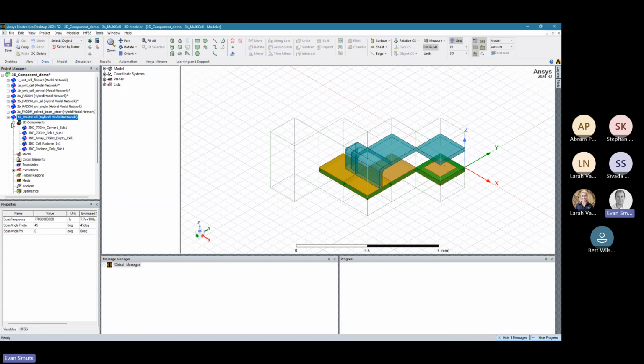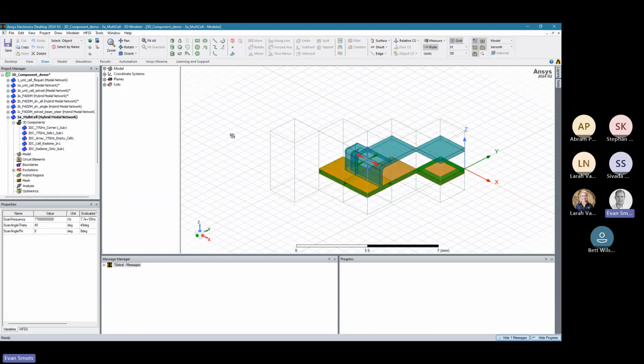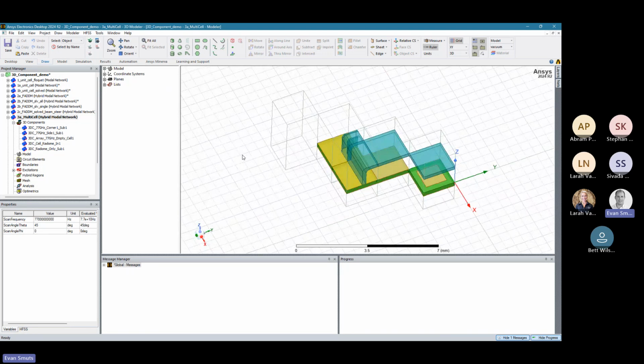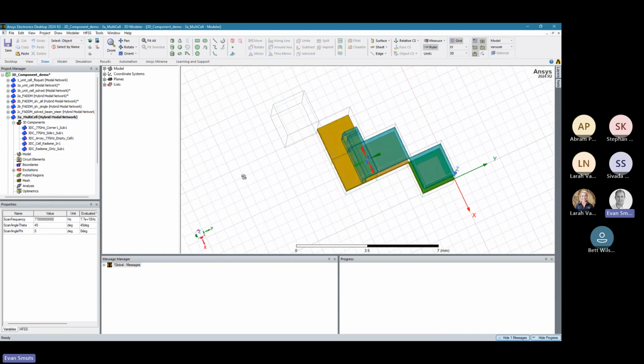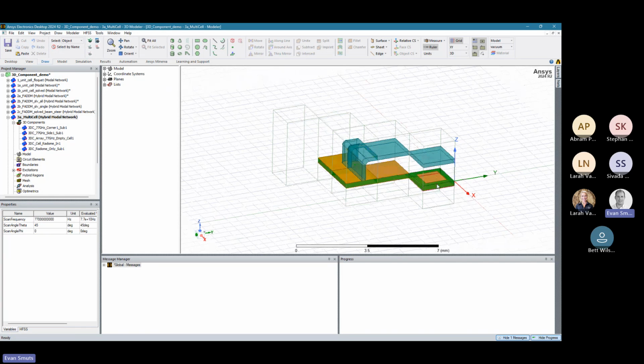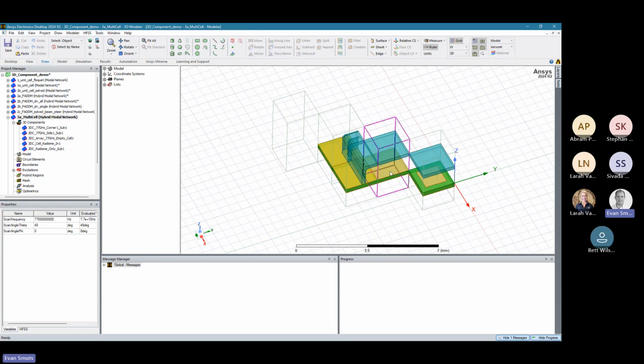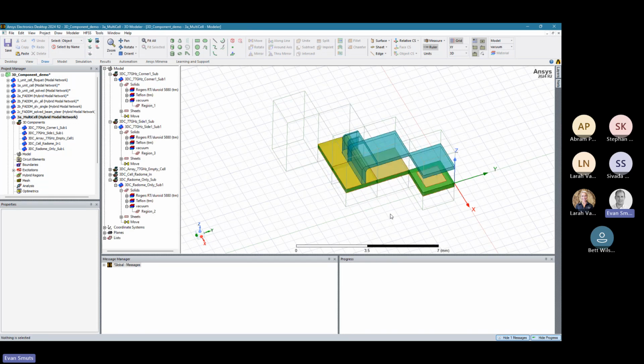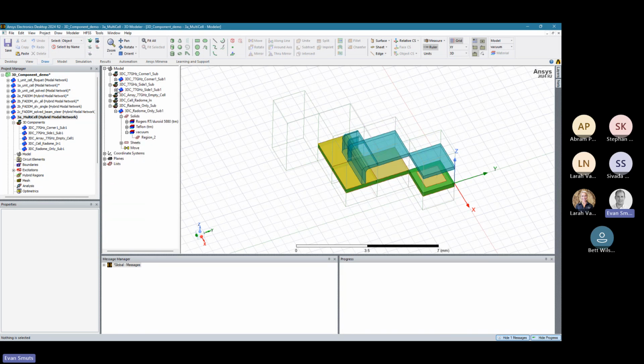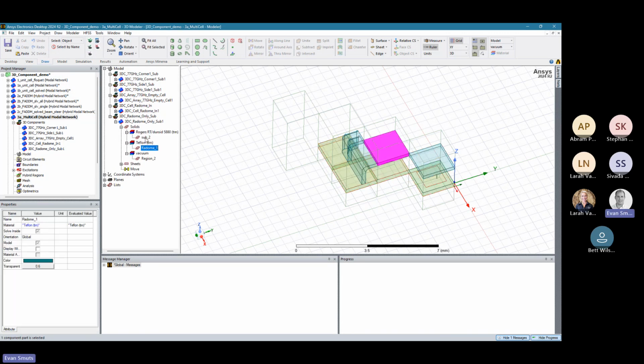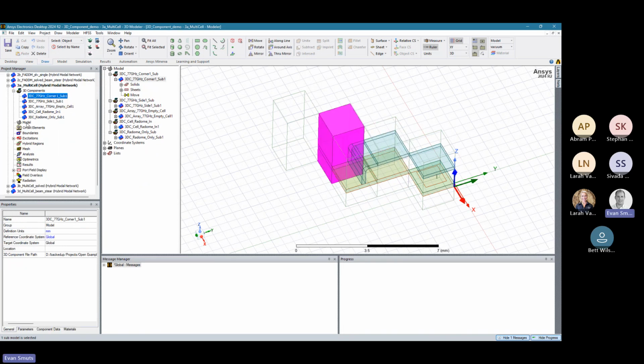And just lastly, to show you here for the multi-cell approach. This is just a slight evolution of what we've seen already. In this case, we've got a slightly more complex array. It's the same patch antenna with radome, but now we're going to include the sides of our array. So we've got additional elements here that make up the geometry around the side of our array, so we can take into account these edge effects. You can see here that we've got all these different bodies, and they all come in with their own materials and shapes and everything. They've been imported here under 3D components.